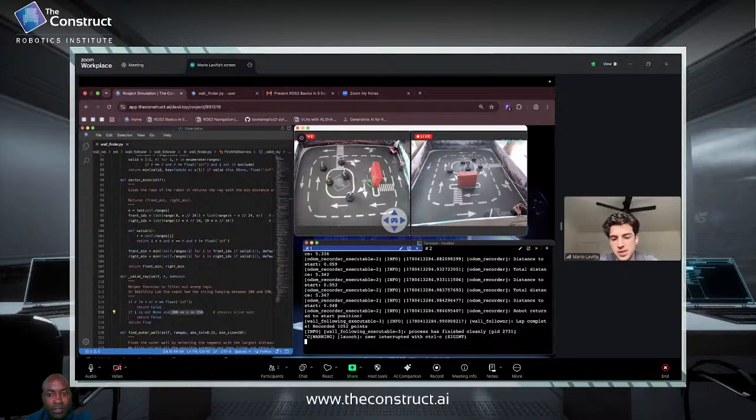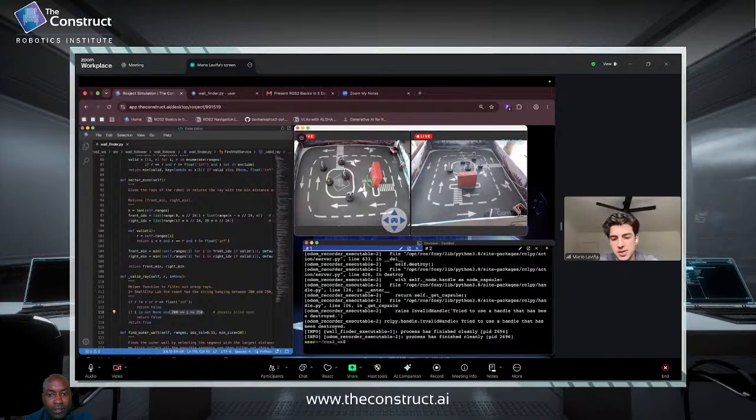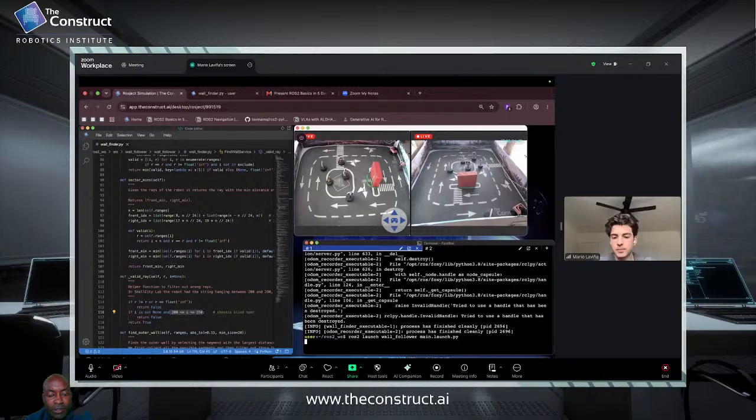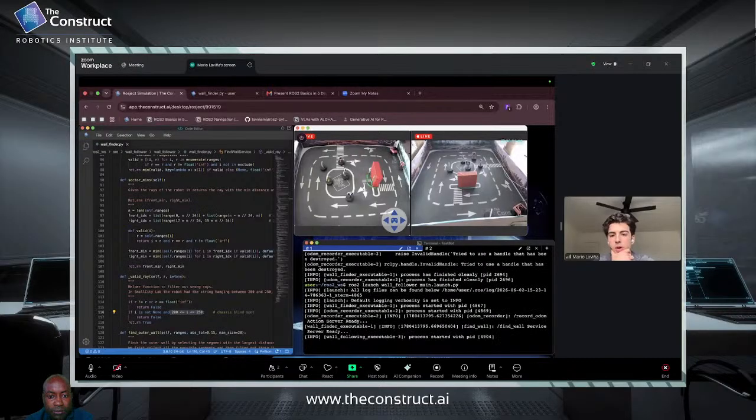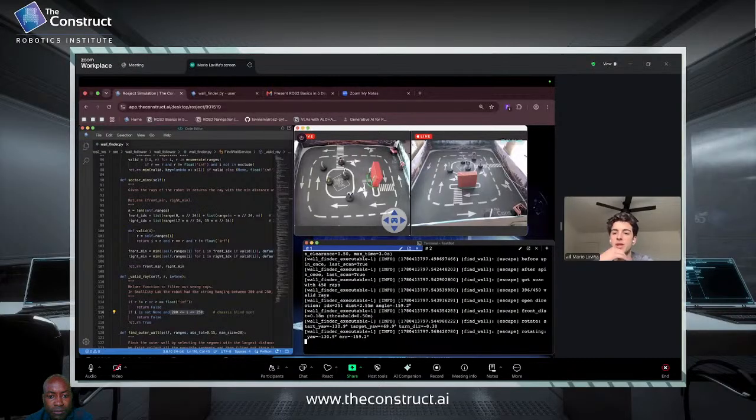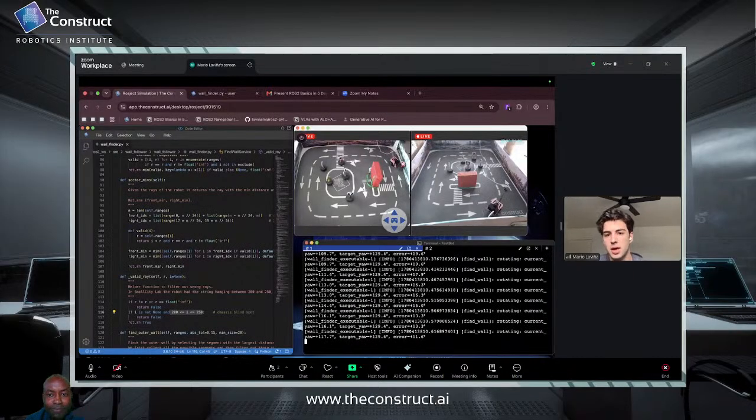So if we run this project at the same time, what I do here is I have a previous step to finding the outer wall. If it finds two outer walls which are both too close to each other and also very big segments, it goes to the most open space. Once it finds the most open space, it goes about 30 centimeters away. Then it starts the outer wall finding process, and then basically the wall following process.